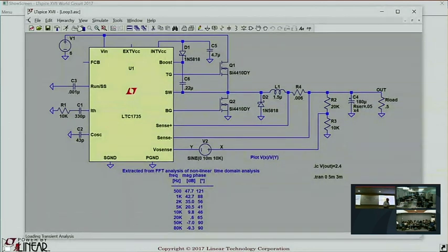Here's the thing. Where frequency domain analysis has gotten some traction, has become popular, and is canonized in our study is what we should know about. It's useful if the situation goes like this. Say you go all the way around the feedback loop and you find which component values give rise to the poles and zeros. Then you might think of a strategy where you will change a component value to move a zero to cancel a pole to make the thing stable. That would be useful. And that is exactly what is entirely impossible in a current mode buck.